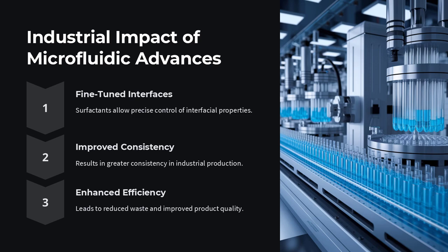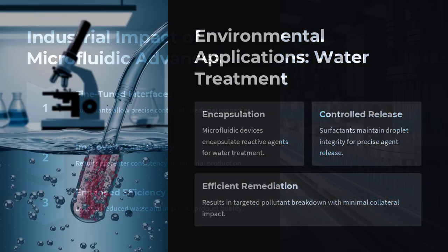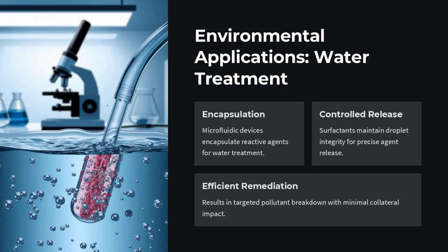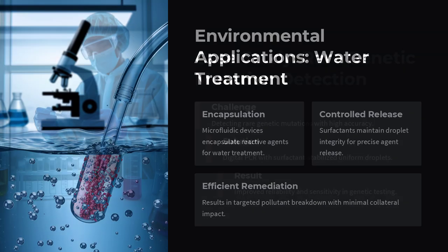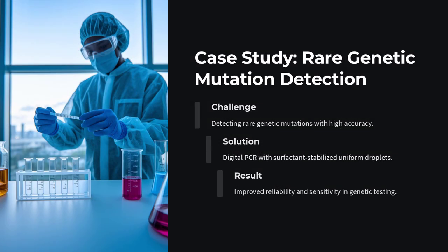In the context of microfluidics, using an insufficient amount of surfactant could leave the interfacial tension high, resulting in droplets that are prone to instability and coalescence. Conversely, an excess may lead to the creation of micellar structures that could sequester important reactants or disrupt the overall flow dynamic. When asked what happens under these circumstances, the answer is that precise calibration of surfactant levels is essential, and advanced analytical techniques such as tensiometry and high-speed imaging are employed to monitor and adjust these concentrations in real time.